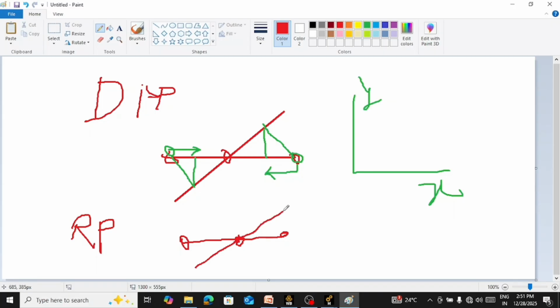Now, when you apply the boundary condition in the case of remote displacement, the boundary condition is applicable only to the RP. So the RP should not move in the x direction, but these nodes can move while maintaining the constraint equation.